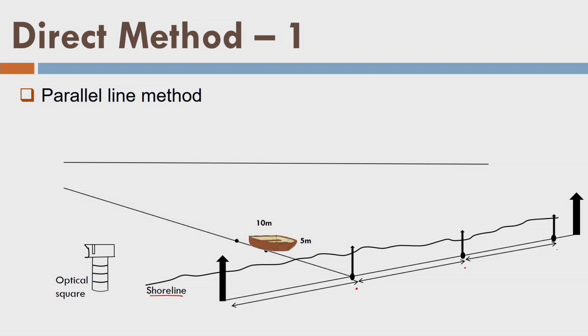So this is the first survey line, which is in the transverse direction to the reference line. Now we stretch the float line. Let me tell you about the float line. One end of the float line is tied at the reference mark,